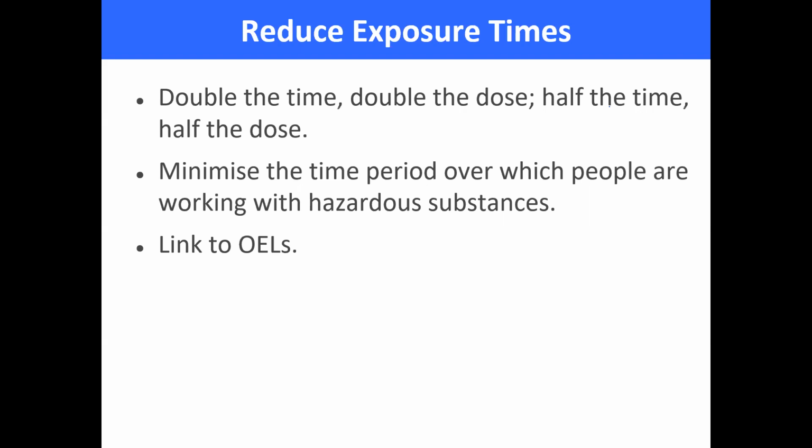Okay, reduced exposure is also very, very important. So you need to remember the rule of thumb: double time, double the dose. If the dose is increased, you can automatically consider that the time of exposure has also increased, or if your time has doubled, it means you have received a double dose. So make sure you minimize the time period over which people are working with hazardous substances. Don't allow them to work continuously a full day with hazardous substances, and make sure this exposure is linked to OEL.